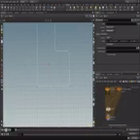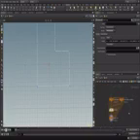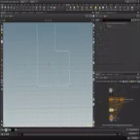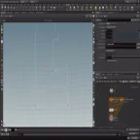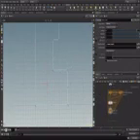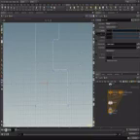And to make sure this is as fast as possible, right now it's a very small thing, but just to see how we can put this into a compiled loop, let's place down a null node. And this null node is going to contain the amount of prims, so n prims, because we only need to loop it once per prim, and then it's all done. And we could make it do random prims first, but it doesn't really matter that much. So let's take this value and type in n prims.